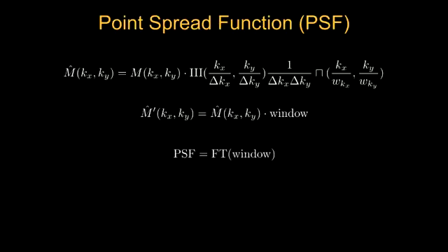You can multiply whatever you want, here we are multiplying by some windowing function. That's purely your decision. But you also need to understand the trade-off. To understand it, apply the Fourier transform of that windowing function. It's called the point spread function. The point spread function is the way to assess the trade-off of the windowing function, or whatever manipulation of the k-space data.